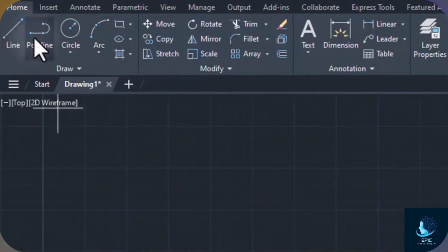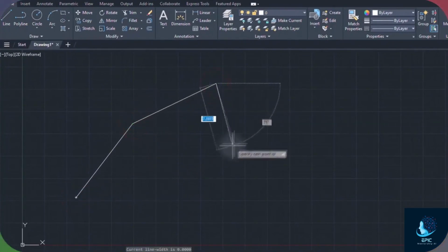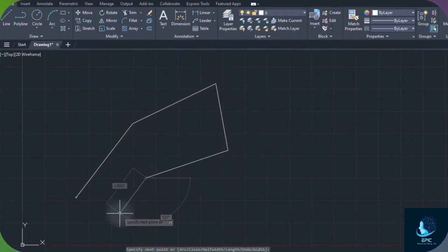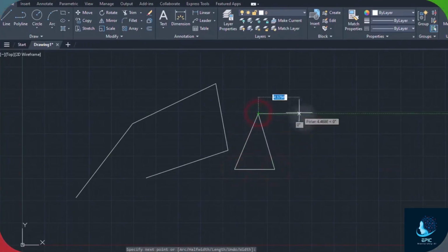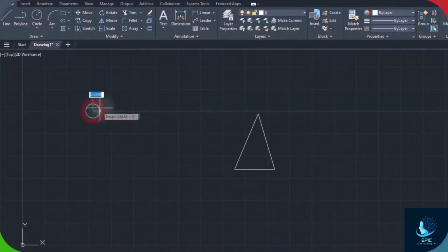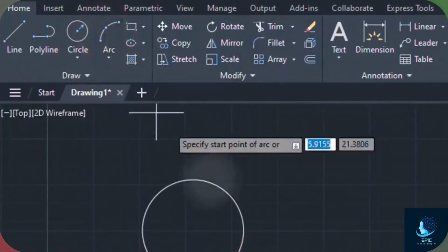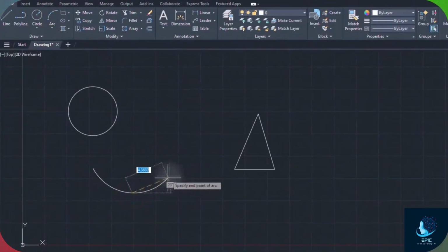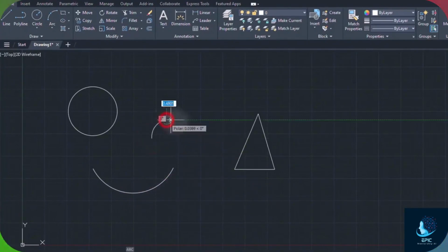Enable the Line or the Polyline tool and click twice on the preview to draw a straight segment. You will go on dropping others until you press the Escape key to stop. You can enable the tool again with the Enter key. Enable the Circle tool to drop a circle with 2 points. To draw an arc, enable the Arc tool and drop 3 points instead. Press the Enter key to enable the tool again and drop another arc.